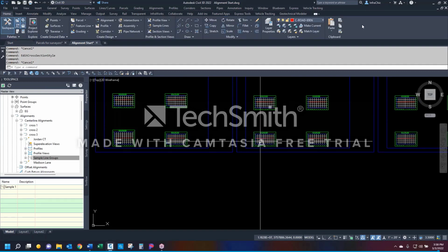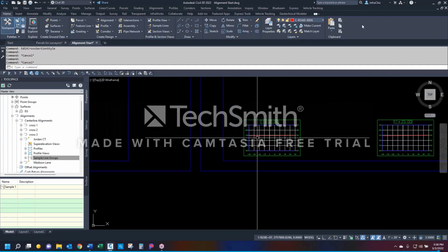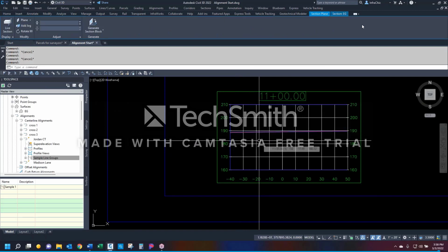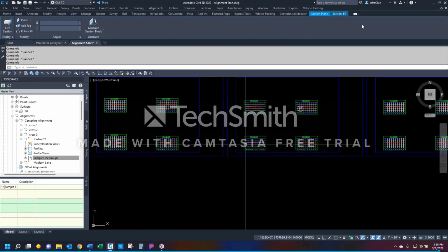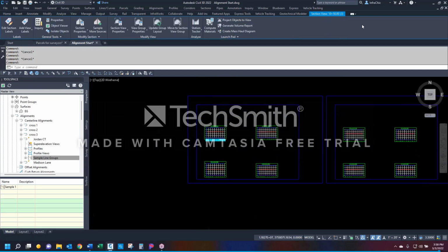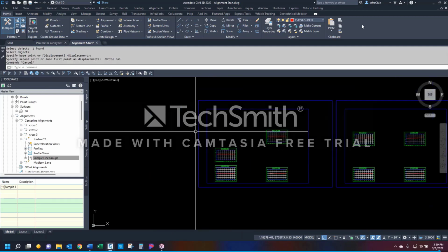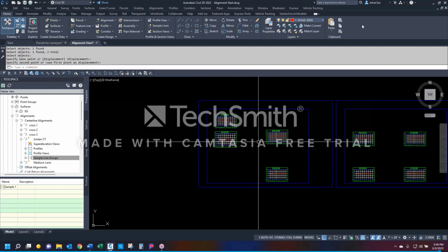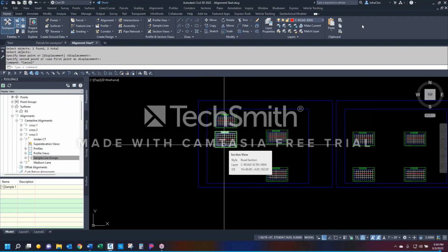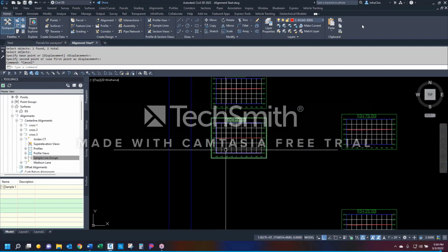So this is like the profile. The section view has its own grid, and this line representing existing ground is the section itself, okay? Two separate things. You can move these by grabbing any part of the grid and just moving it. This is like the paper example, and I will say in sections you can draw plain line work in here, and when you move the grid, the plain line work will move with the grid. That's one of the newer features in like 2018, 2020, to be able to keep any line work and text that was drawn within the boundary of the grid, on the grid, and moving with the grid.